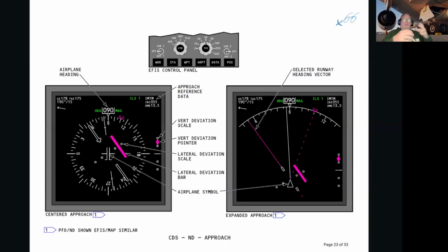And if we have a stored flight plan inside the FMS, it will give the pilot a recommended route from A to B and say, all right, so the parameters you've given me, the weight of the aircraft, the amount of fuel, your initial starting point, your destination, your requested altitude, the wind, the barometric pressure, and all of these factors, plus the weight of the passengers, the final weight, fuel weight, everything, catering. This is the flight plan from A to B.